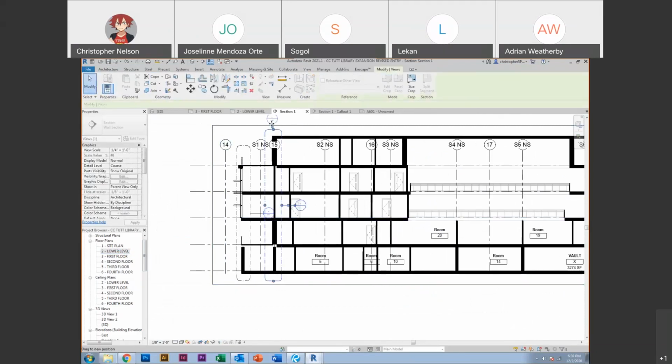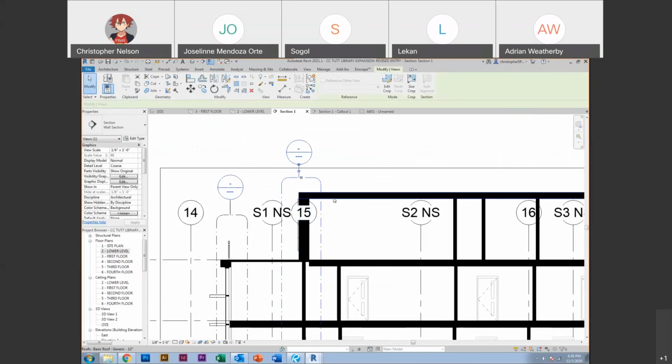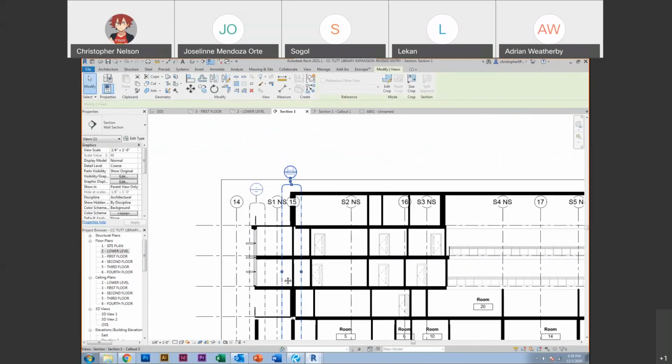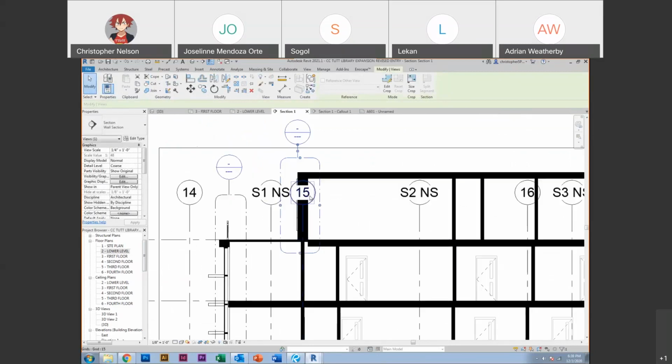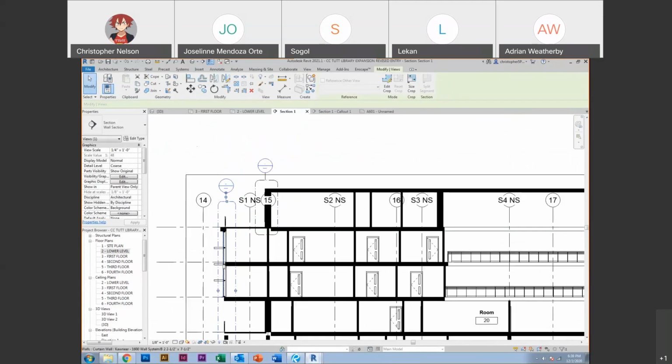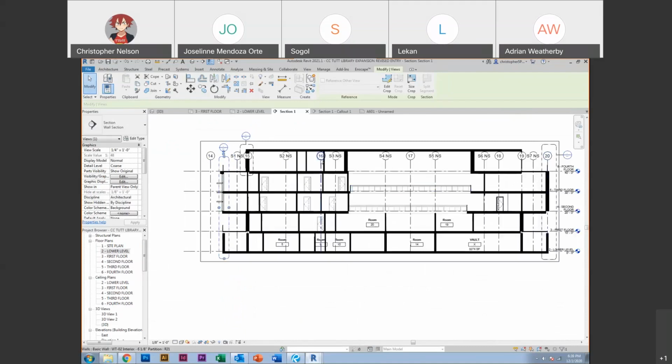Most times when I say wherever you need it, wherever you have an exterior condition that's different, you'll have a wall section. And they don't always need to be for the entirety of the building. So where we have another level and a little roof plane, you could literally just make the call out be just of this one area. And then the other one will go top to bottom, right? But that way, you see I've cut 3 of them right now.